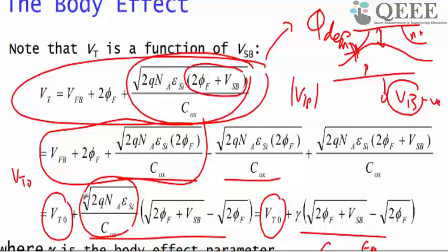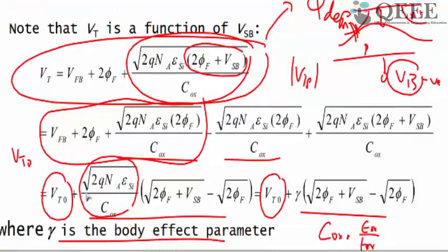Earlier I mentioned you can still apply some positive bias voltage, you can slightly forward bias the junction, but you do not go into much. The advantage is that you can reduce the VT. In the same way, when you apply negative bias, your VT increases. When you apply a small positive bias, that bias has to be less than something like 0.6 volts, because you do not want to turn on the junction. If you reduce the VT, your current will increase.